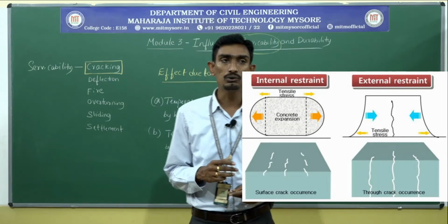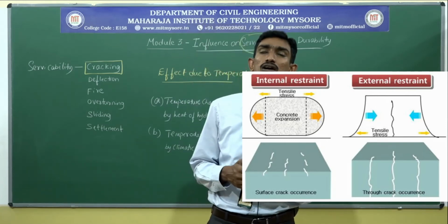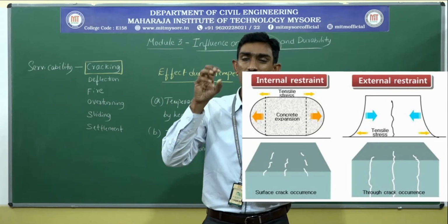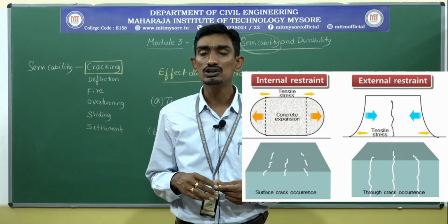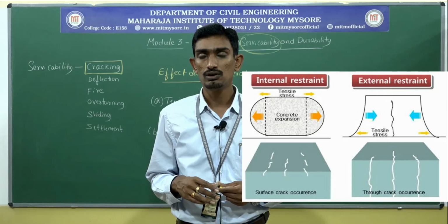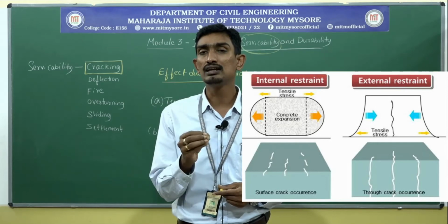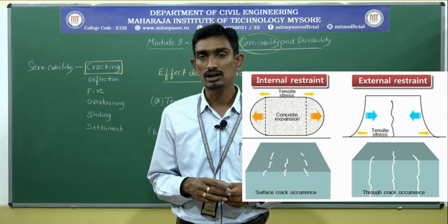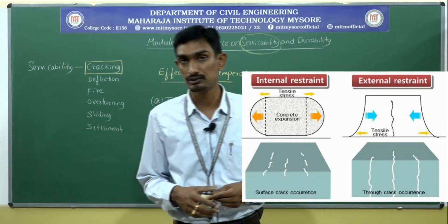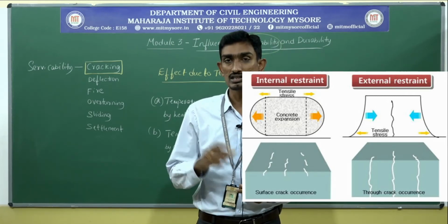So that's why I want to highlight a very important point here. Nowadays, concrete practitioners or concrete technocrats who want to design a concrete mix for a particular condition or a particular place also need to keep temperature in mind. By keeping temperature as a key factor, you need to design a concrete mix. The next point is climatic conditions. There I will also quote some examples of how exactly the behavior will change in winter condition, summer condition, and variations in climate.